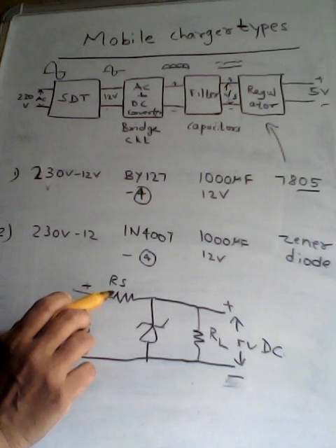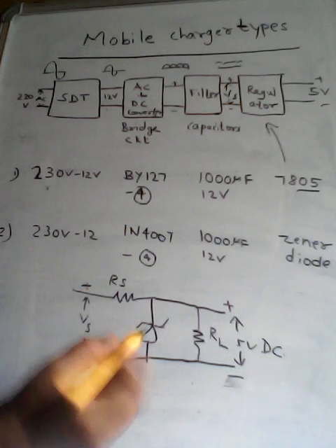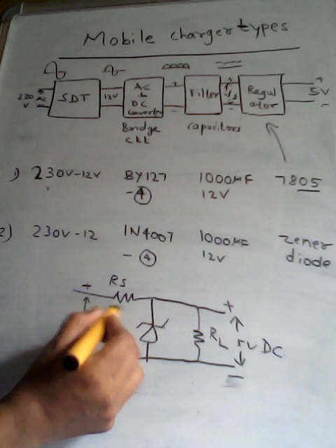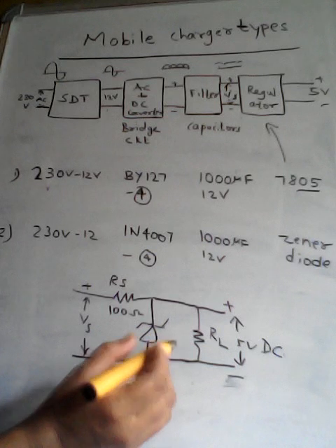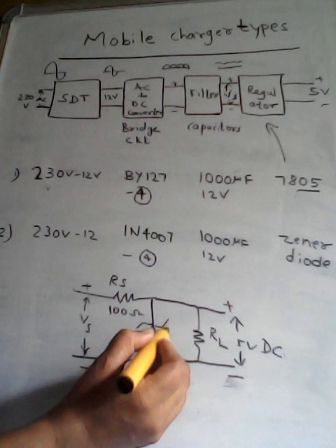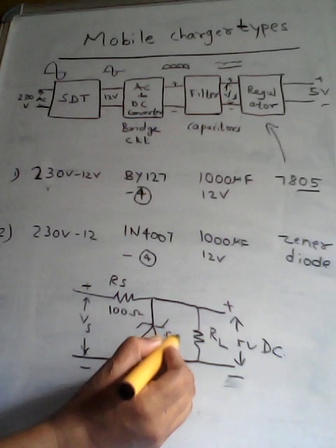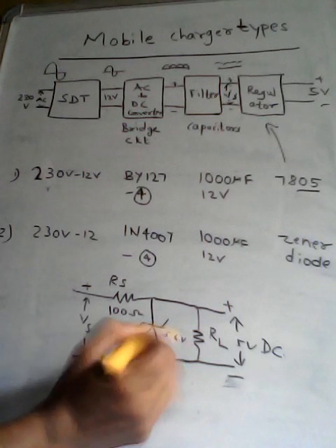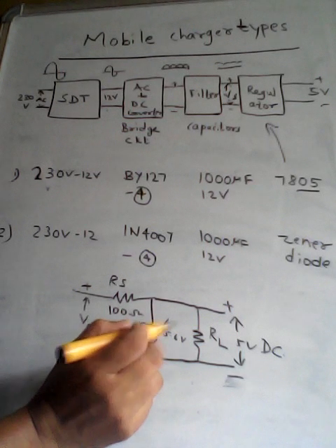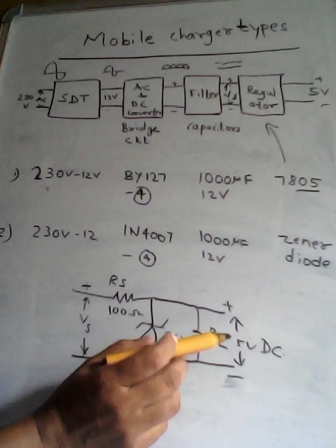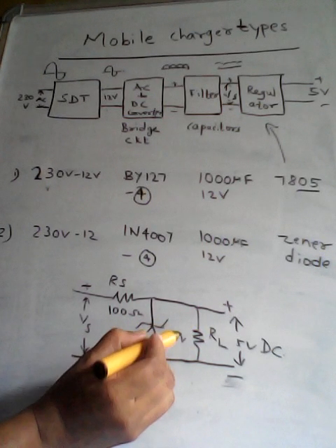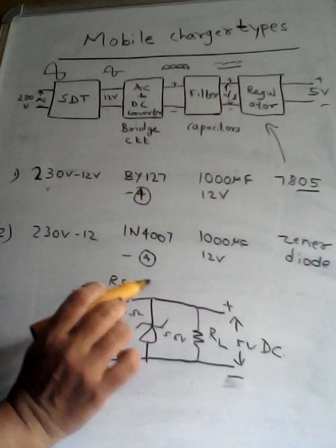And to connect this we can make use of 100 ohm resistor here, and we can use a Zener which may be rating from 5.1 to 5.6 volt here, which can provide that much voltage, and this will provide constant 5 volt at its output, even though there will be slight variation in the output.